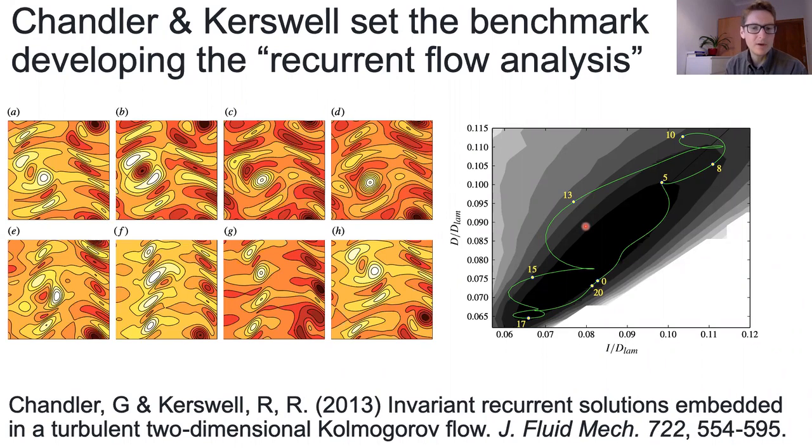They were finding, in this two-dimensional Kolmogorov flow, which I'll talk about in a second, orbits at certain Reynolds numbers on the order of 50 or 200 orbits in one set of results. In this way you can start to use them as an expansion for your turbulent flow, and consider how best to add them up and weight them to give you a reduced order description.